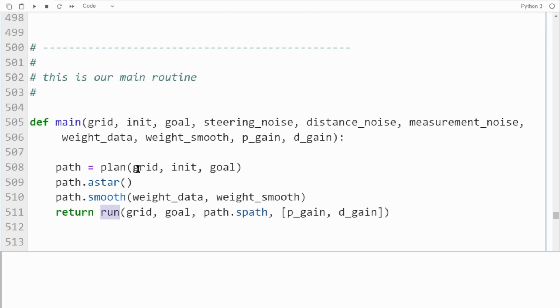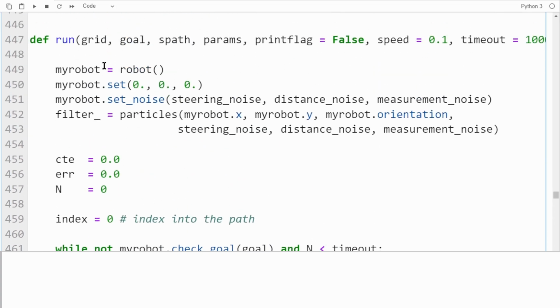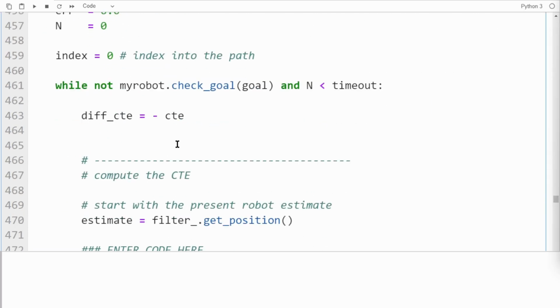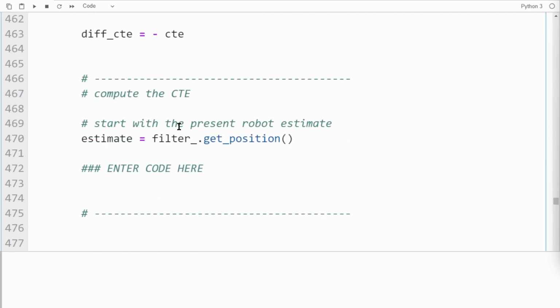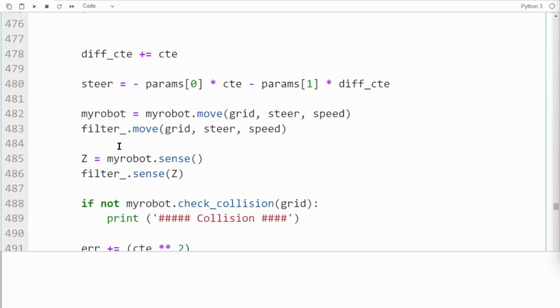And in the controller, I even implemented for you our particle filter that you're familiar with. There's nothing new here. You're running the exact same code from class that you programmed yourself. And then I go through a loop where I compute a cross-track error, apply my only PD controller, there's no I term here, and I run my particle filter as before to estimate where the robot is.